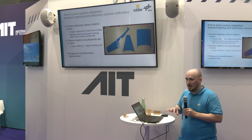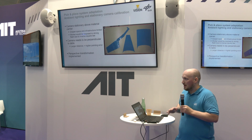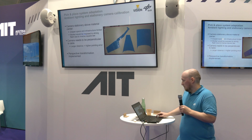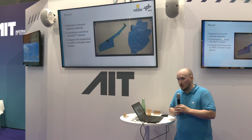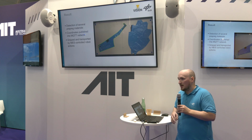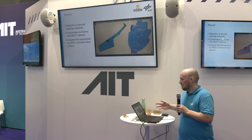And this is needed for our cut piece localization, since we use pattern matching, and the pattern is in 2D, and to have the same sizes we need to be perpendicular to the cut piece to have the same area we are looking for. And then we tried it out, and we detected several materials, and you can already see here that the ply isn't very uniform. It has cutouts to measure fiber angles on the cut piece. It's wrinkly, it's reflecting heavily, but with the contrast enhancements we could do with the color camera, it was really easy to now also detect these parts.